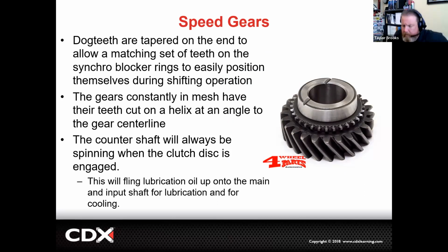So in the case of our S40 transaxle, it does have kind of a channel ducting system that allows for gear oil to be directed, once it's flung up and fallen into its trough, to different components, and it can spill out onto some of the speed gears. But the bearings that are inside of this need to be frictionless because they're expecting to not really run with a ton of lubrication, not at least pressurized lubrication. It's a non-pressurized system inside of there.